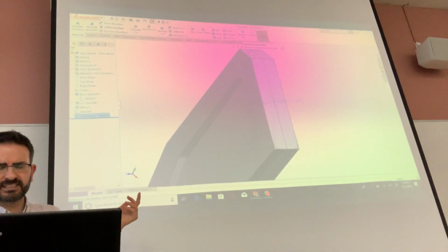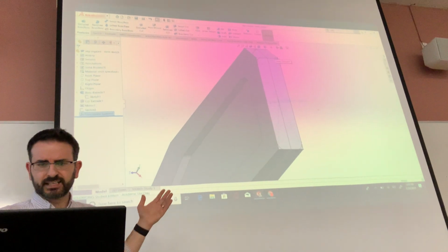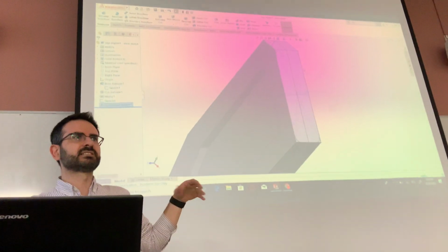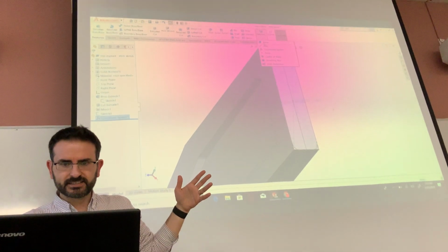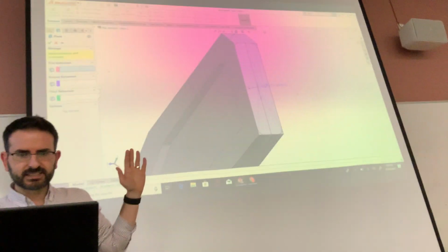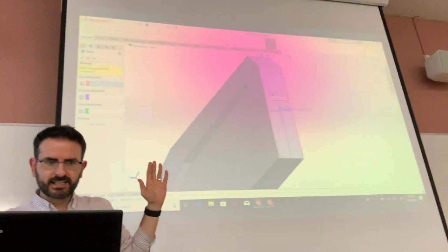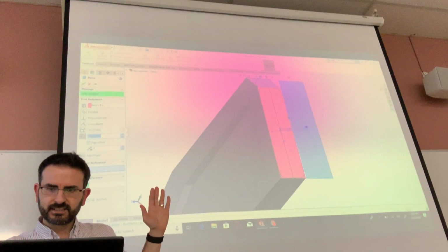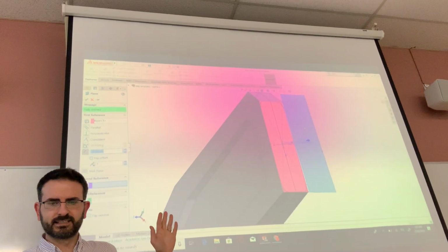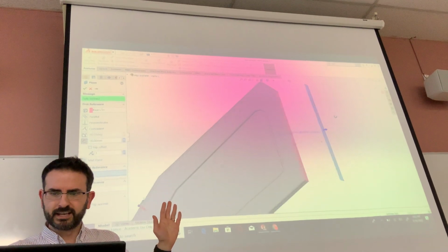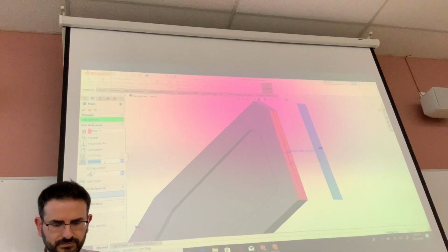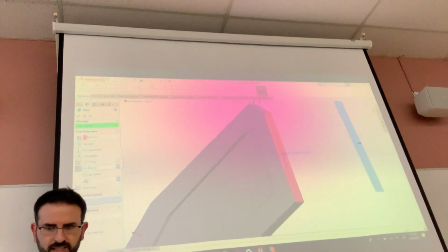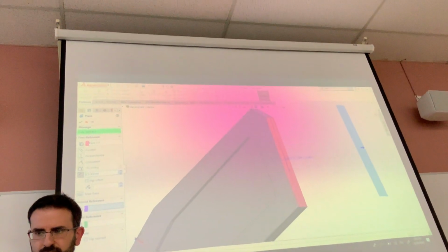In this case, I probably didn't need to create the coordinate system for this specific task, but it's useful nonetheless. So let's see. Create a plane. Okay, the first reference is gonna be this actual face here. Okay, it's happy with that. So it's already created a plane. Now all I need to do is say how far, and that's 25 millimeters. Okay, that looks good.